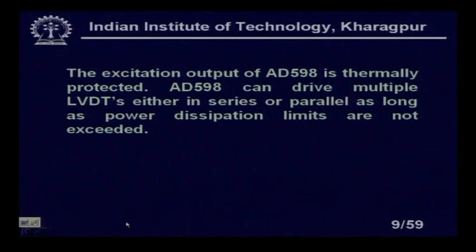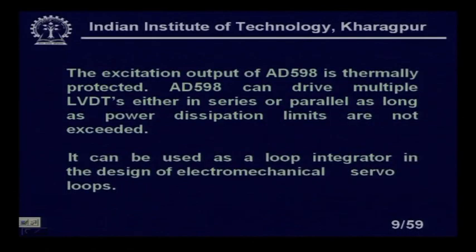The excitation output of the AD598 is thermally protected, and the AD598 can drive multiple LVDTs in either series or parallel as long as power dissipation limits are not exceeded. This is a great advantage. The same chip can be used for several LVDT excitations. So, that is a great saving in cost. It can be used as a loop integrator in the design of electromechanical servo loops.